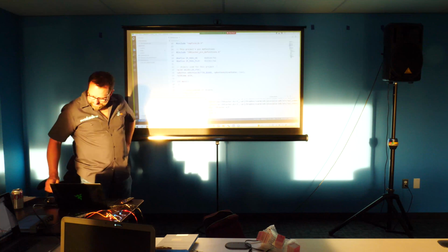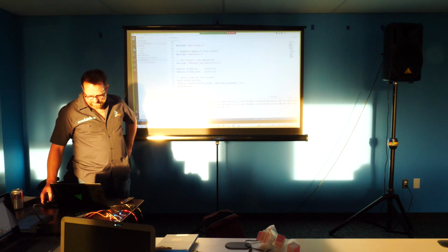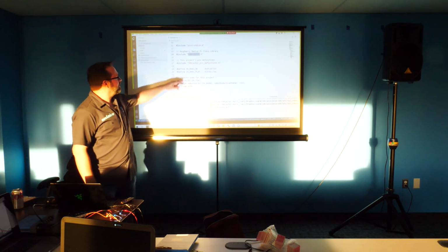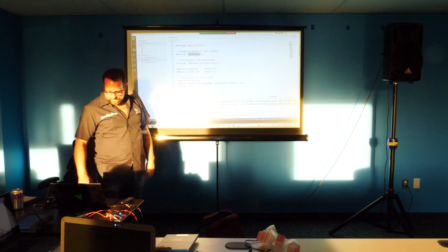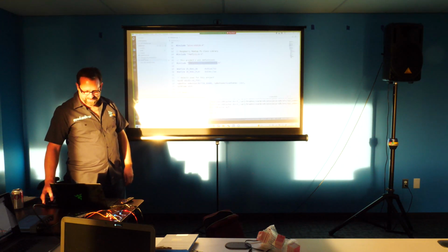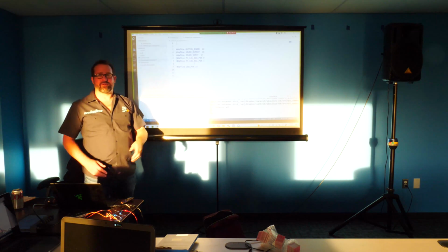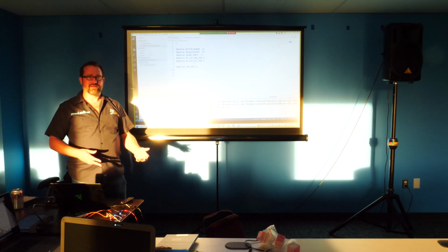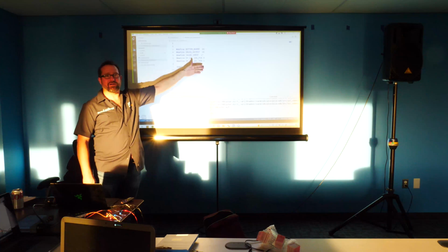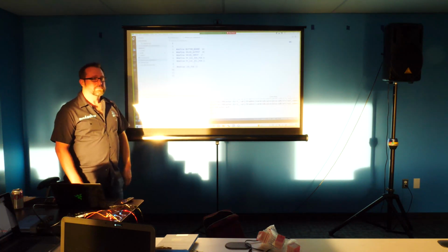So just going through the code, we include the library. This is the class library that we created, and I'll show you what that is in a second. Then the project pin definitions. A good practice is to put that in a separate file. What's good about that is you can create different projects that use the same code, and all you do is change this part of the file when you change the pins.